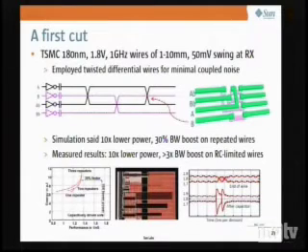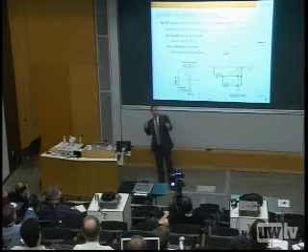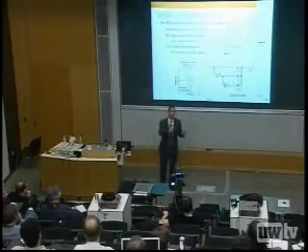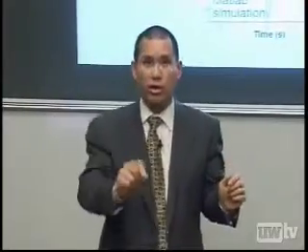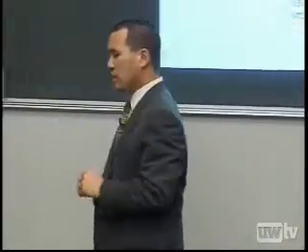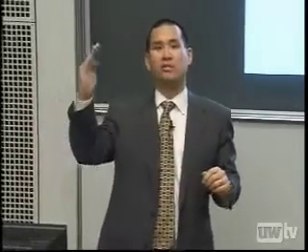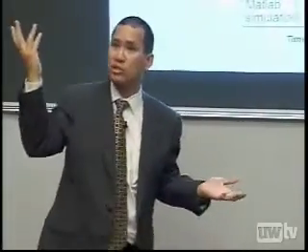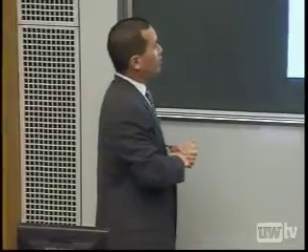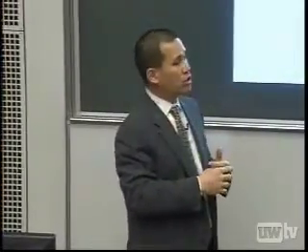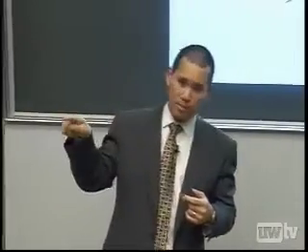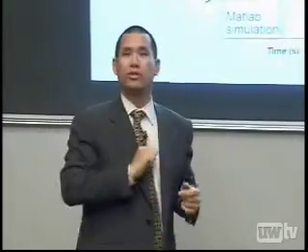It seemed reasonable. Well, then we said, hey, we can make some observations here. One thing is, if I send a data bit in a non-return to 0 format, 0, 1, 0, 1, then what I usually get is a nice fast rise followed by a slow tail. It's an RC circuit. Okay? So if I could do a return to 0 signal, so an upward pulse or a downward pulse, okay?